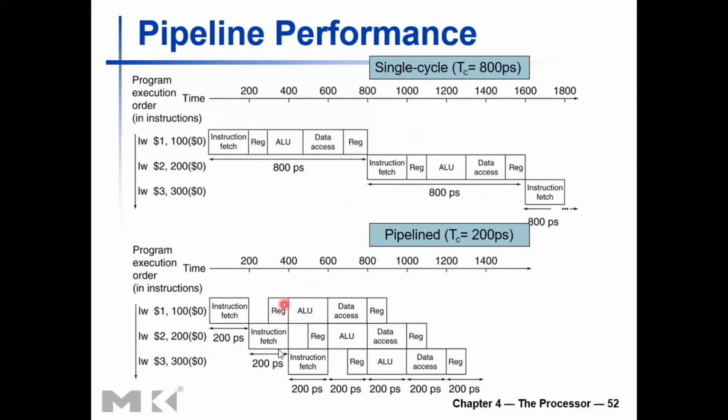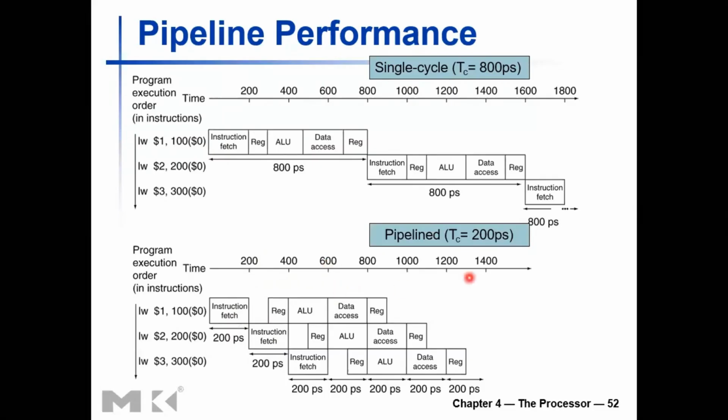And we aligned each stage into one clock cycle, a smaller clock cycle, and bring the instructions in a staggered manner, one after the other, in each clock cycle. So all our hardware units are utilized better compared to single cycle implementation, or even a multi-cycle implementation, which is not pipelined, right?